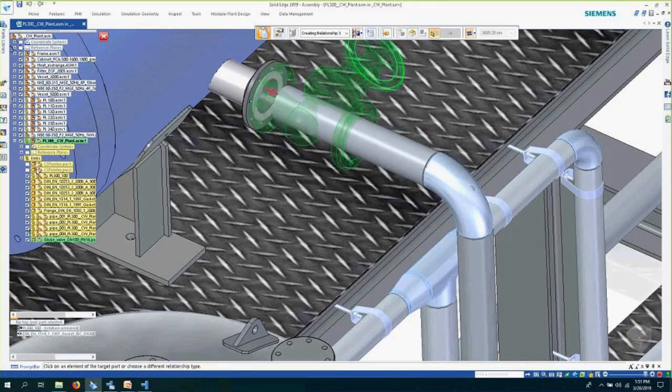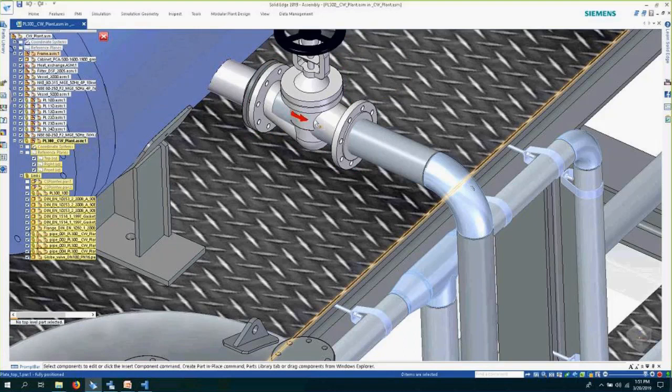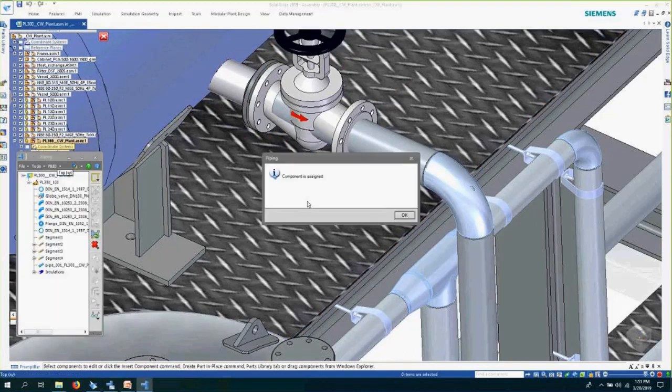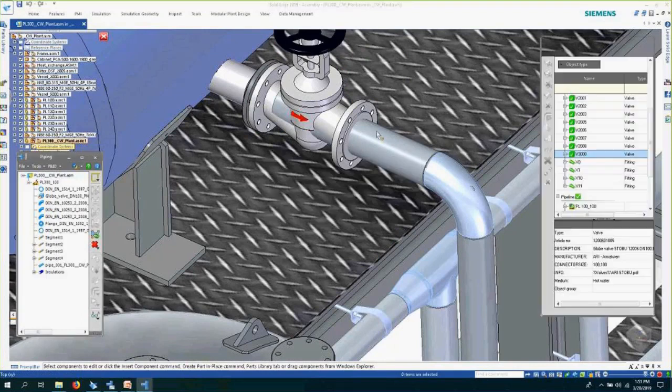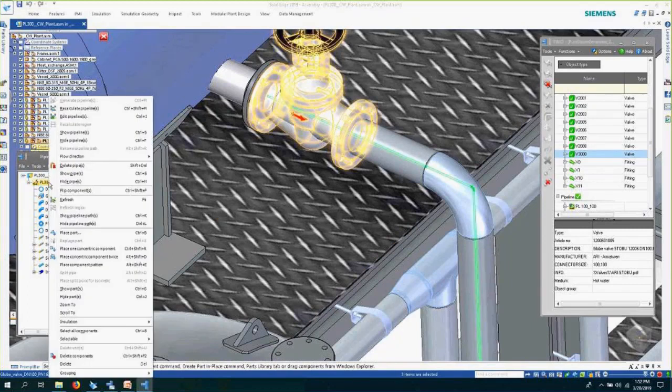And so we can actually have all of our capture fit information already added in here. Again, just base Solid Edge functionality of building my assemblies. So I get it placed into here. Life is good. And then I can come in and tell it, all right, let's update all of the pipes and make sure that there's no finished connecting information that might be missing here.